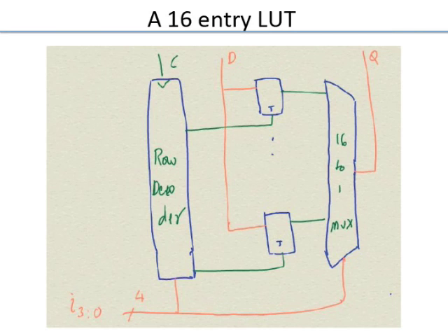Though you don't want to write at a particular instant, the clock will be coming high. Correct. So I don't need to put a clock here. In that case, I'll just put a write enable. Instead of a clock here, I'll put a write enable.